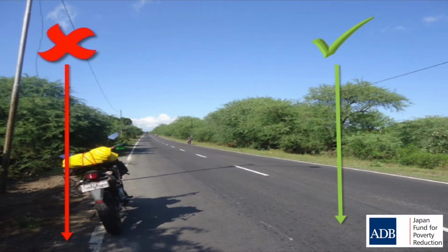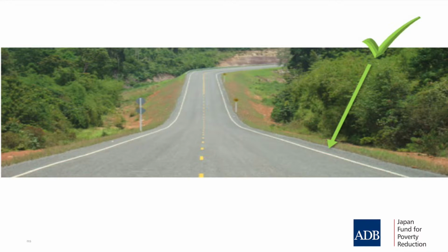This is why I say this is a very nice road, very good surface, good pavement. A lot of money has been spent building this road. And it's very good. But if we can have sealed shoulders like this, it just provides that bit for a motorcyclist to escape a vehicle coming at them.